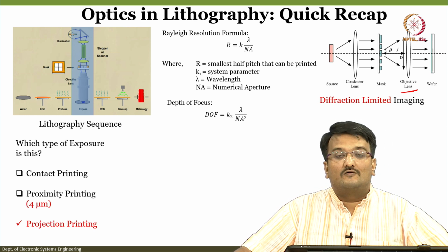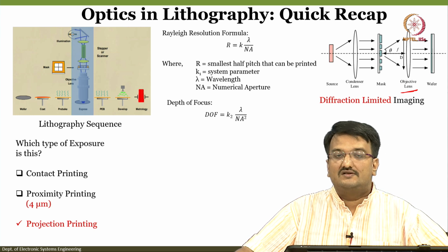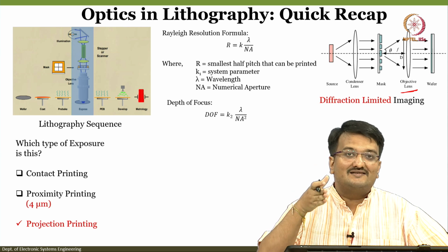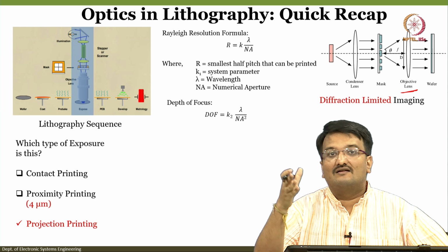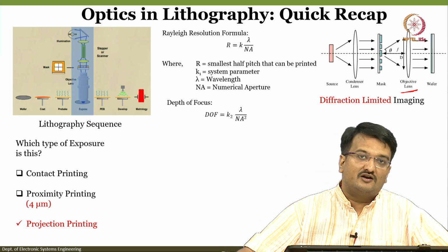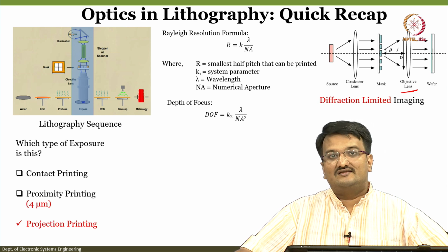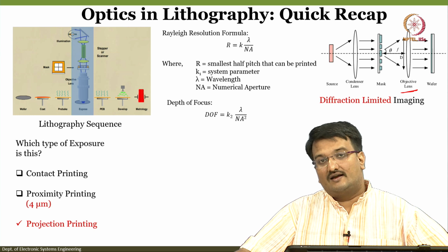that is what your depth of focus is. Now, the higher the value of depth of focus, it is better for you because you will get a chance to place it here and there a little bit. Precise placement comes with its own challenges and cost. So, we have to consider all these parameters. I also mentioned that numerical aperture, higher the better, but it will also affect the depth of focus. So, that is another point. We have to make a trade off out of it to design and get a proper resolution.